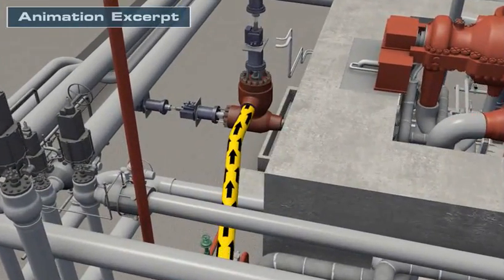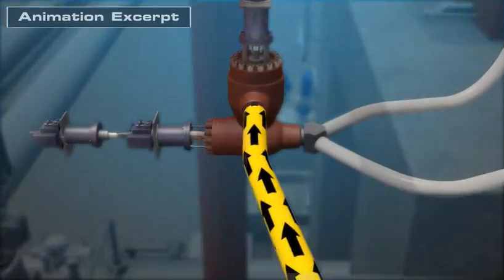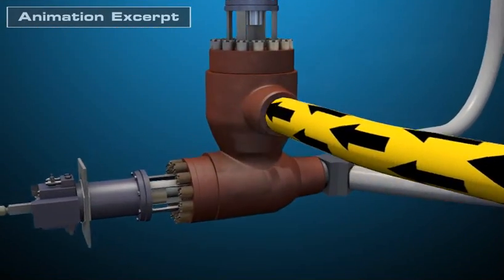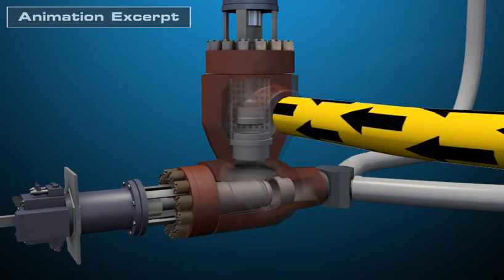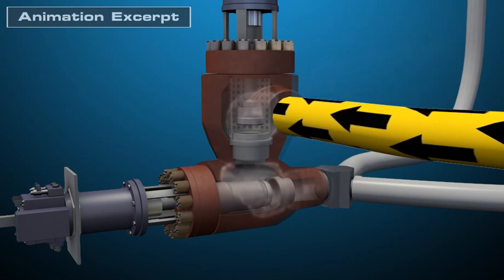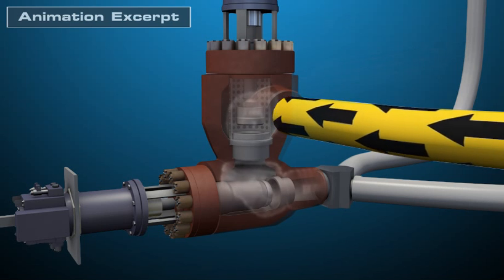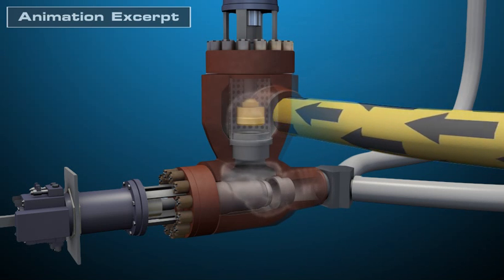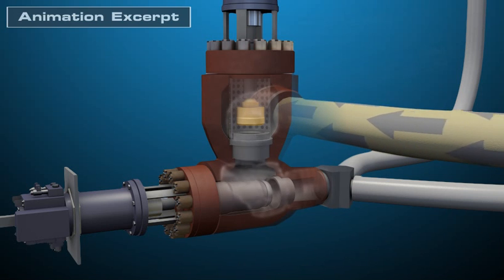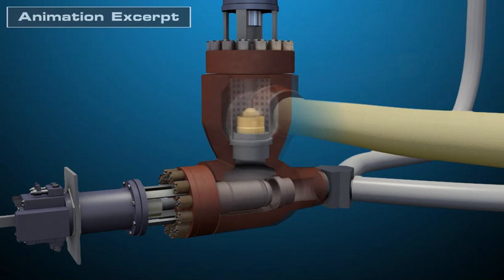The main steam line connects to a single combined main steam stop control valve, or MSCV. The 2 valves operate independently of each other, but share a common casing. The stop valve portion of each MSCV is also used for quick and complete isolation of main steam to the steam turbine. The stop valve is slammed shut any time a trip condition occurs with the steam turbine.